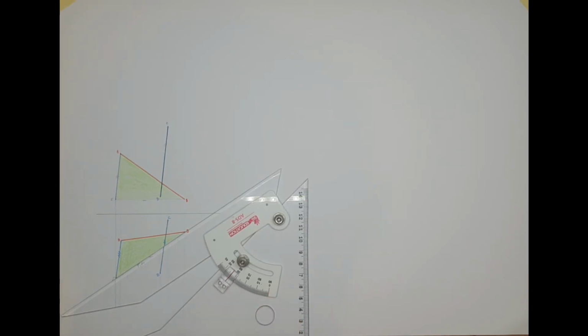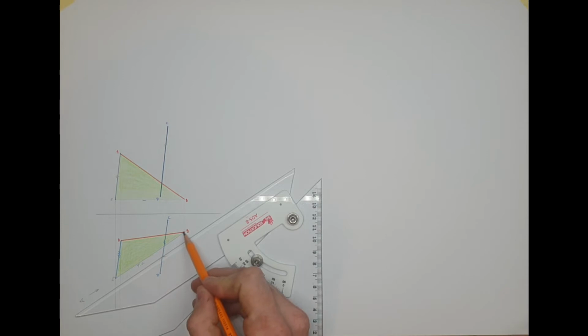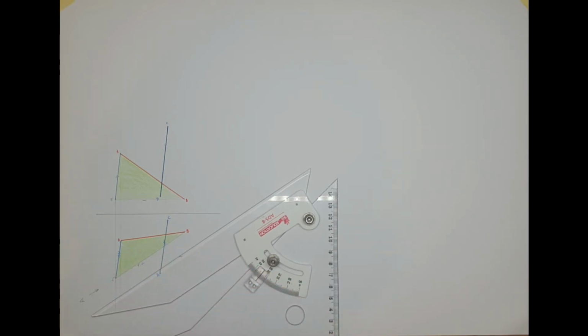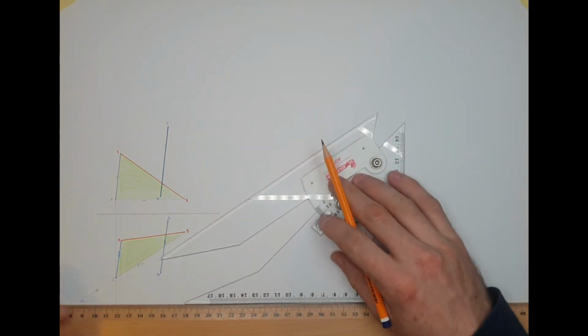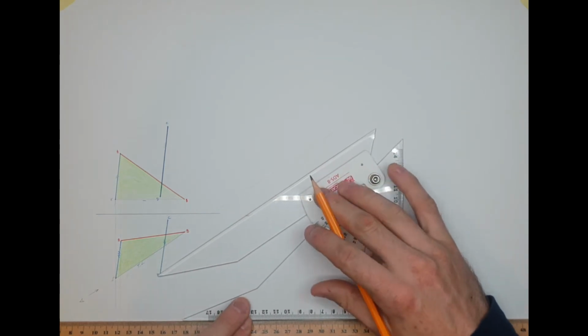If I view along that line, in this direction here, I should get that line EB appearing as a single point, and I should get the plane ABE appearing as an edge view, and what we saw earlier on in the model, I should also get the red line and blue line appearing as 2 parallel lines. So let's see how that works out. We project everything up,